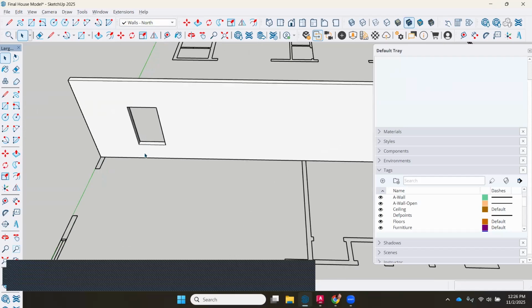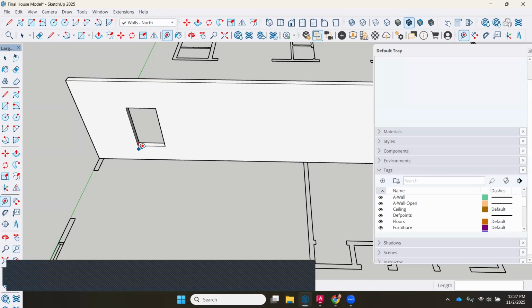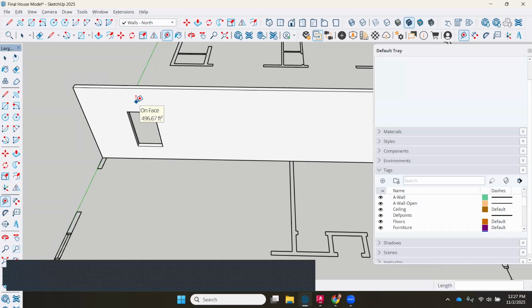Now you're going to go online and find a window block on the SketchUp warehouse that hopefully is 3-foot wide by, let's see, how tall is this one? 5-foot window. That's a pretty standard size. Try to keep it to a full foot or 1.5 feet, so go in foot increments or 6 inches, like 1'6", 2'6". Those are the standard sizes they come in. So that's your windows. Also, when you're looking for a model, look for one that has molding all around it already.